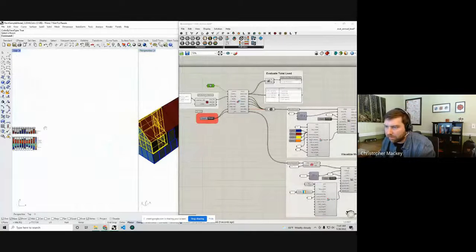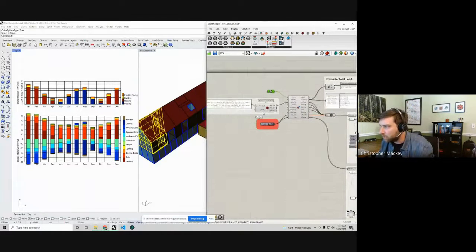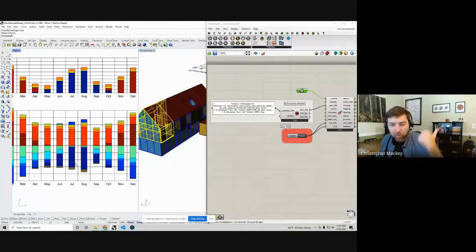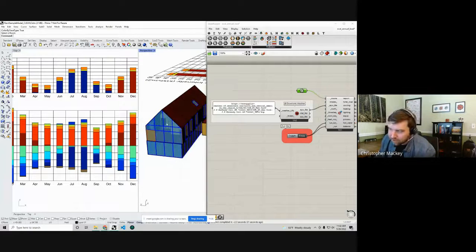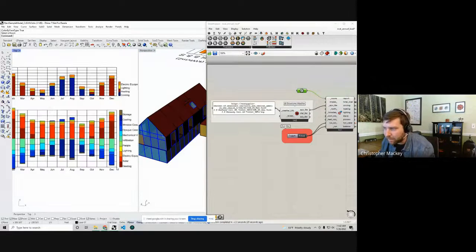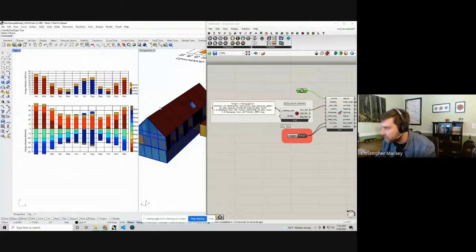And if I go over to top view, you can actually see we're getting out a load balance of just this room from our Pollination model. And we can see that what is really driving the cooling energy of this room in particular is this really high solar load. Maybe we shouldn't be so surprised, since this is a west-facing, really glassy room, right? It's going to have a high amount of solar gain and a lot of window conduction too, that's responsible for this high heating energy use.